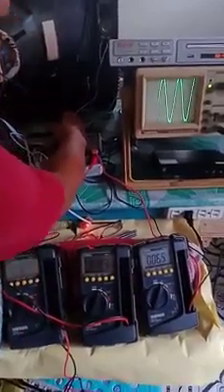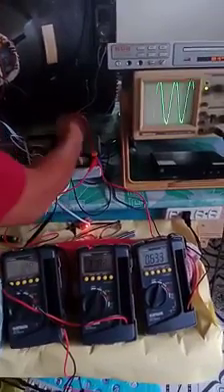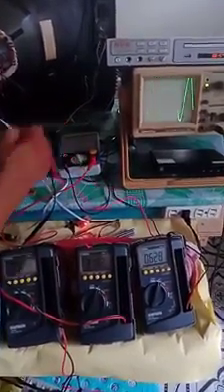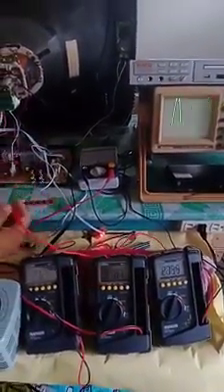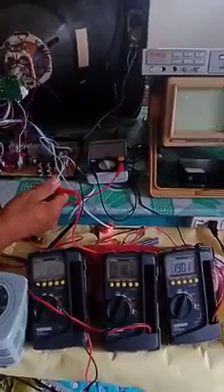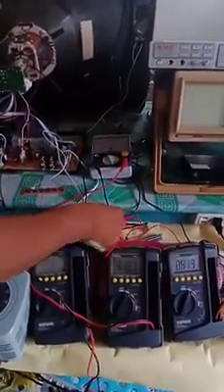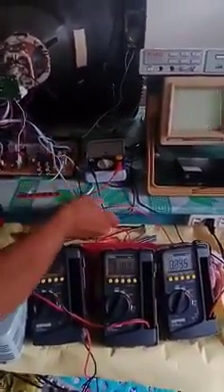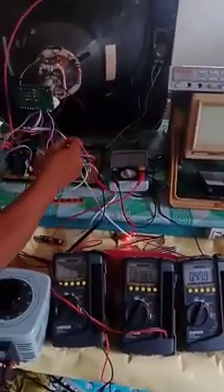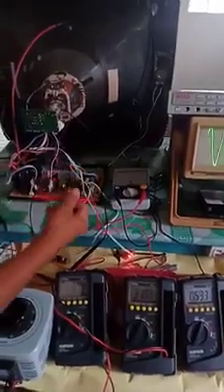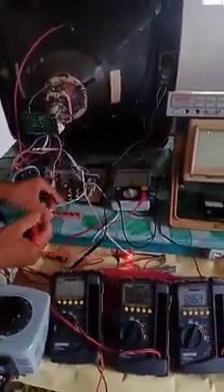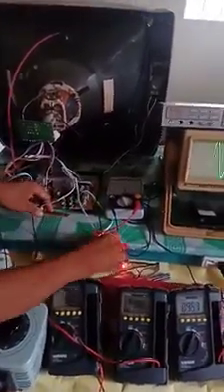So, 5 to 6 volts for the EEPROM, MPU, the keyboard, and the infrared sensor, received from the low voltage power supply. Okay, those are the ways we measure the DC voltages at the terminals of the components inside the circuit. Now, going back again to the infrared sensor.